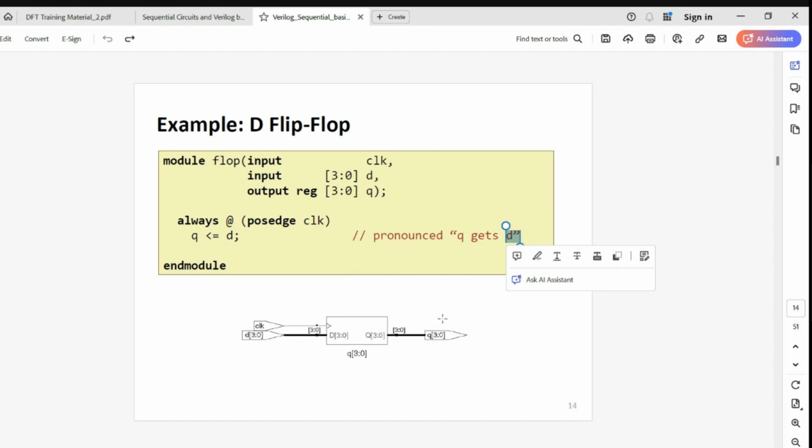When you say 1 output is coming here, that means it is also storing the value. When you say reg, it also stores that 1 value, and also it is at the Q. So if some logic is connected here, that value is already moved on to that logic, and the logic is executed.